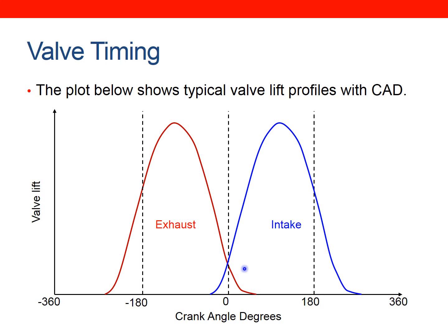So you can see clearly here in the middle, we've got this kind of overlap area, where for a certain time between these crank angles, we have a valve overlap. Now, this is quite important because if you think in terms of what you're trying to do in the engine, this is the compression stroke, and from here to here is the intake stroke. So by the end of here, we want to exhaust all the gases, and here we're just intaking fresh charge. So at this overlap, both the valves are open, and what you're really trying to achieve is a flow where the incoming air is effectively pushing out or scavenging the exhaust products, until this point where it shuts.